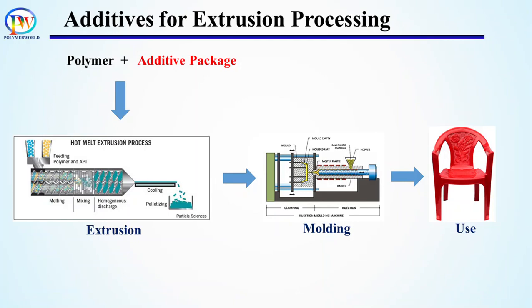Next, and actually the first step where the polymers are required to be protected, is extrusion. Therefore, some specific additives are added to facilitate the extrusion process and protect the polymer during the harsh conditions of extrusion. During extrusion, there are three main factors which can cause significant degradation of polymer chains. These factors are temperature, oxidizing agent, and friction between the polymer chains and screw elements.